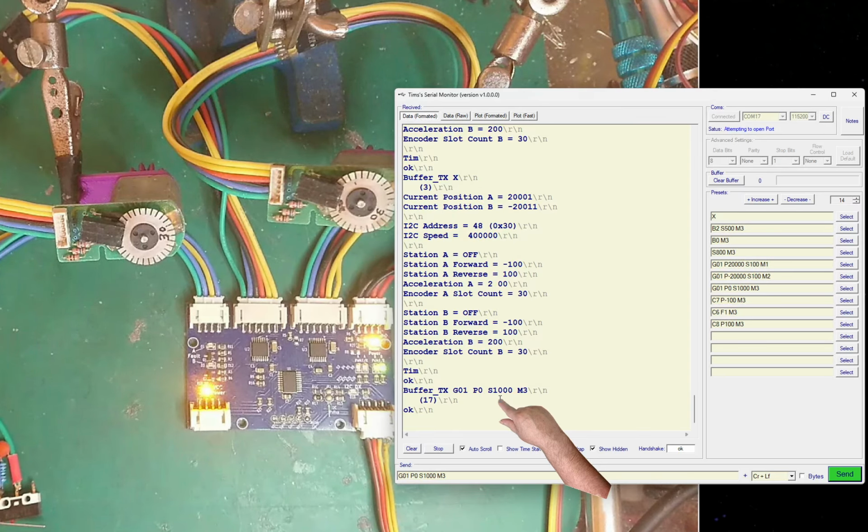So using these variables that we've got now, I should be able to send commands to control both motors at the same time without having to step small increments. I can move one large increment, knowing how long each motor is going to take to get to the position that I want each motor at.